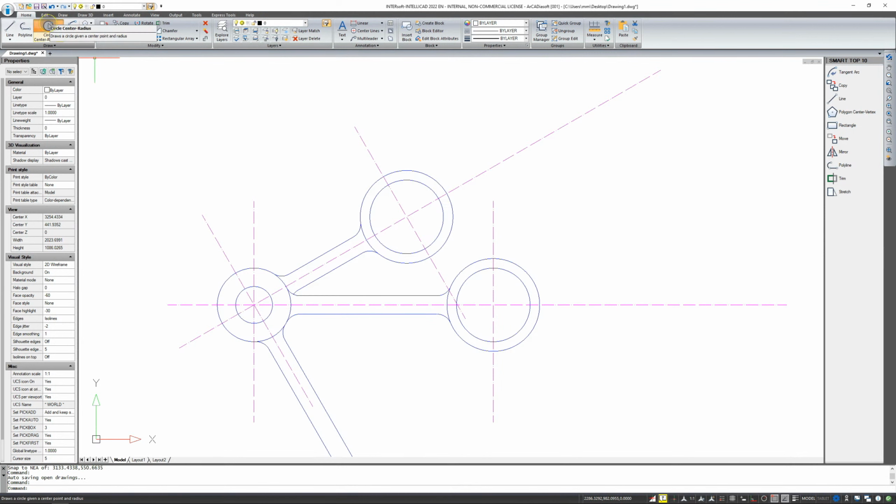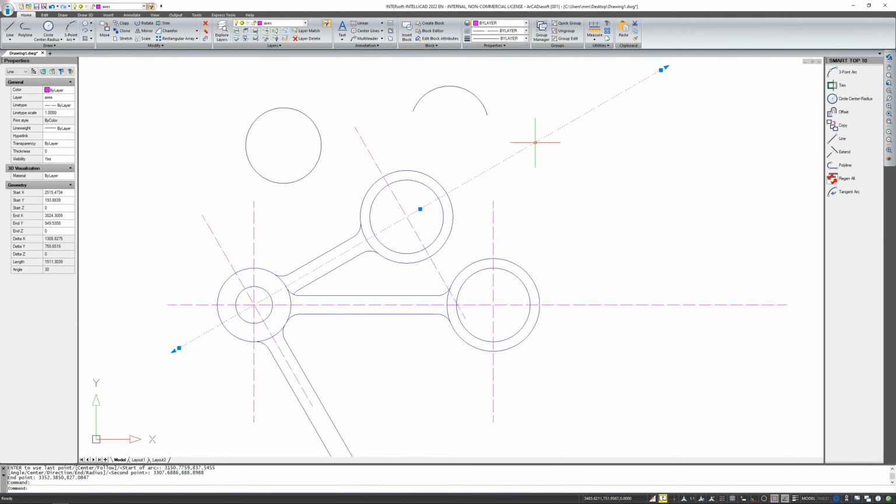And here I'll introduce a circle, some arc. You can see that I'm on a different layer than the axis or my circle. And now I would like to copy all this information about the layer and settings of a given line. I do not copy an element because when I copy an element, it includes its length. I want to clone it because I want to enter the same element but with a different angle and length.